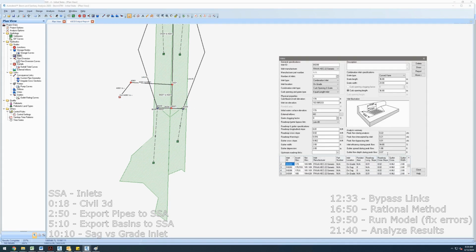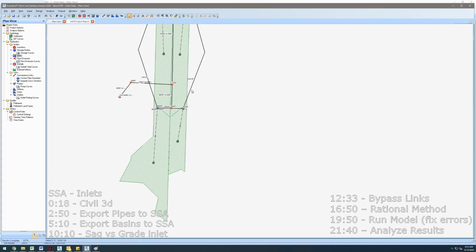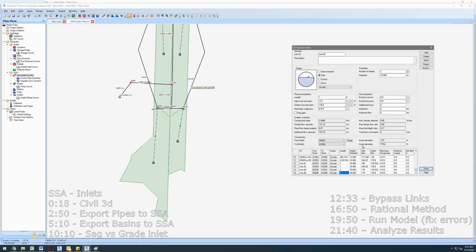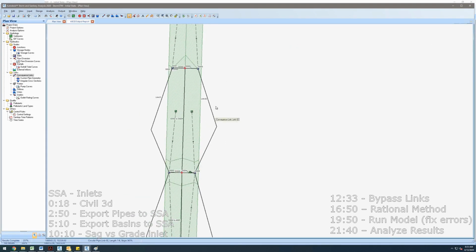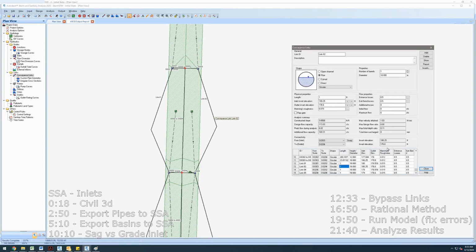This inlet had 1.86 gutter spread during peak, which is not that much, which is good. And it looks like you can click on this as well, and you can see, because I didn't have very much spread, here we go, peak flow, barely anything went over that, which is good. Same with this one, 0.02 peak.